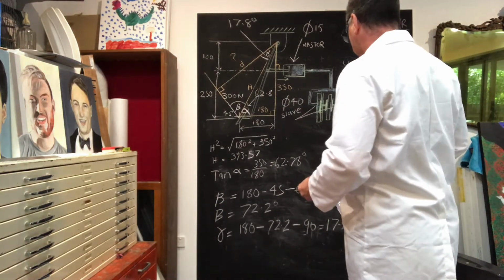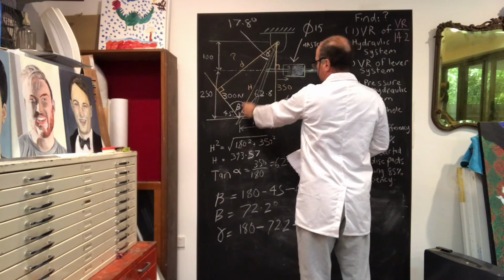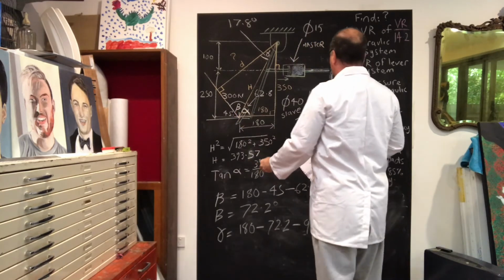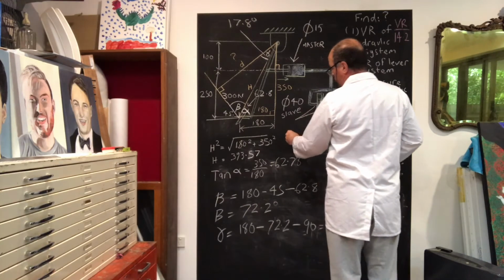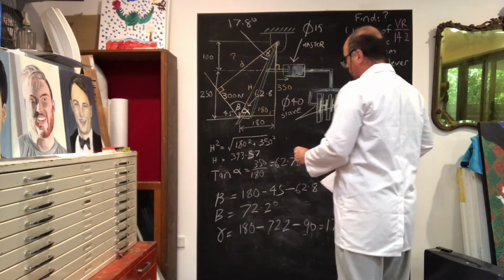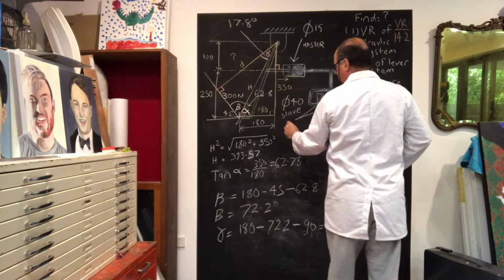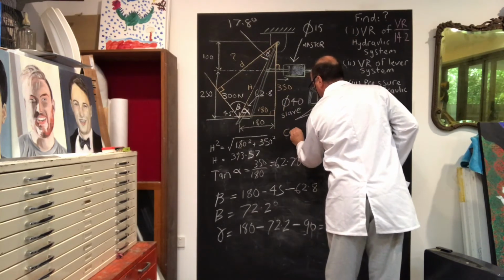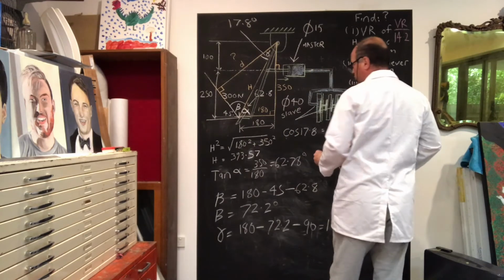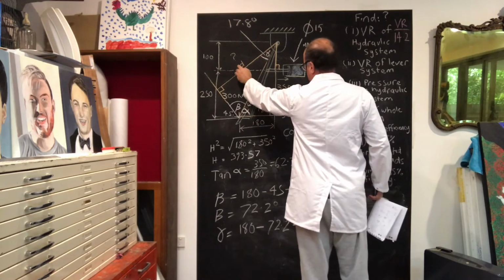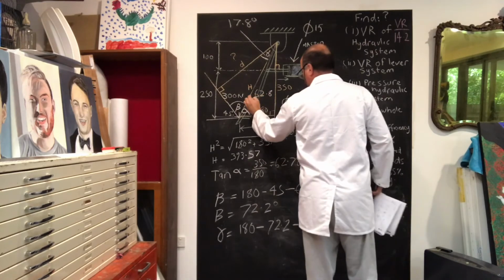So now we've got that angle worked out, it's just a simple matter of using cos to calculate D, because we know that's 17.8 degrees, okay, we know our H, okay, and cos is equal to adjacent on hypotenuse, okay, so we can say to ourselves, for this angle here, cos 17.8 degrees is equal to adjacent, which is the one we don't know, over the hypotenuse, which we did calculate.